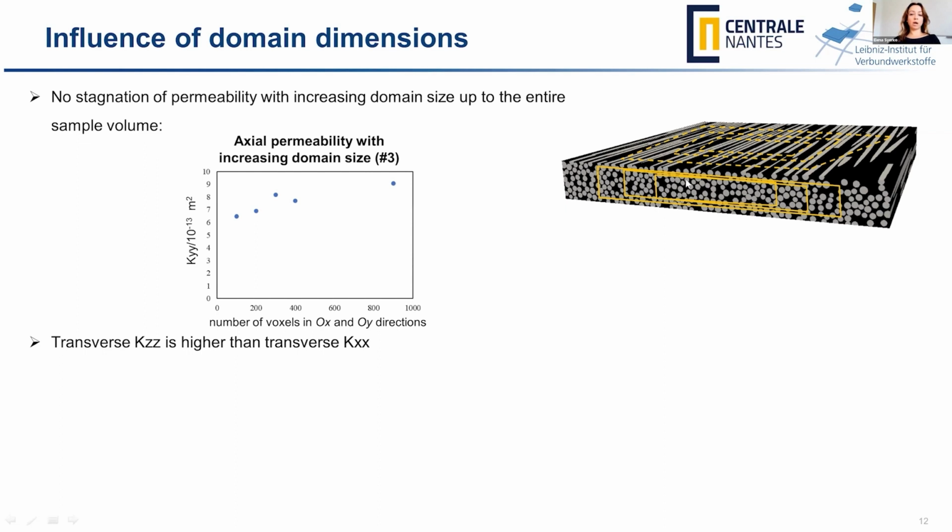And also we have to keep in mind that some of the techniques allow us to preliminarily estimate, by imaging techniques such as texture analysis, for example, how big the volume taken within the sample should be so that it is really an RVE. This can be done by image processing techniques, looking at the stagnation of certain gray level characteristics.